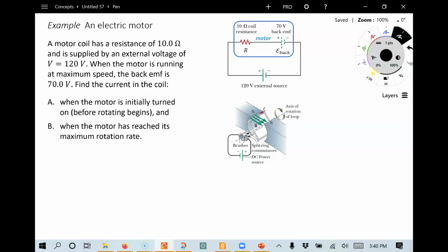Now, in addition to that, we also know that because the magnetic field is passing through the loop, that generates a magnetic flux. And if you think of the normal to the loop, it's kind of hard to draw, but there's your normal to the loop, right? And as the loop spins, this normal is going to spin, going around in a circle.